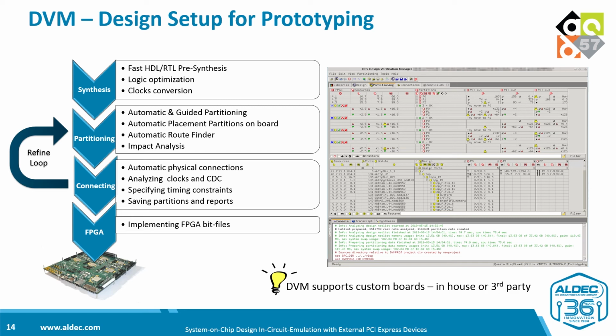It's also worth mentioning that the DVM prototyping flow is available as a separate tool or bundled with emulation modes. The reason for having DVM prototyping separately is that it also supports third-party boards. You can create a board description file in SystemVerilog and, using the board compiler, import it to the DVM and then use all the DVM powerful partitioning features the same way as with Aldec HES boards.